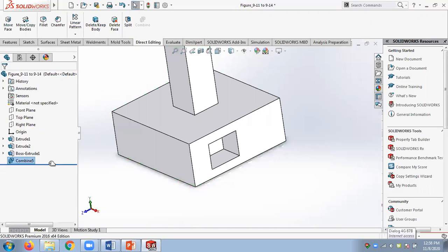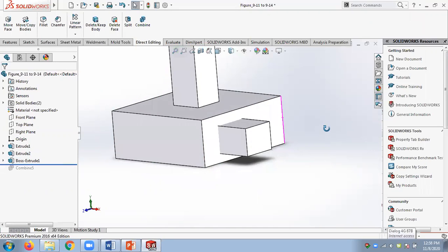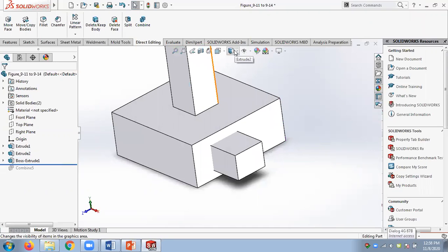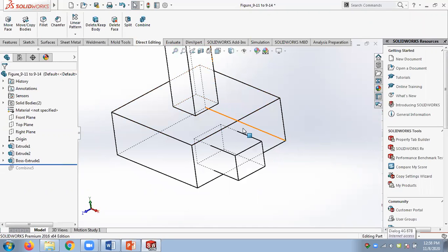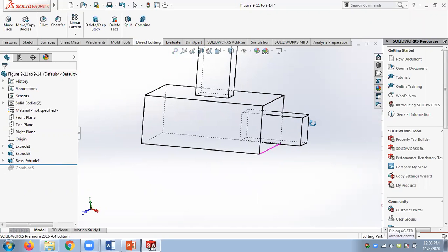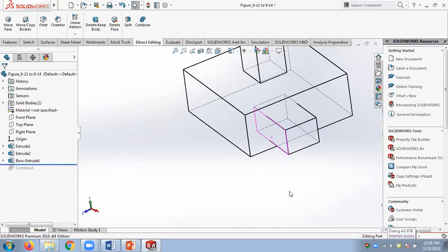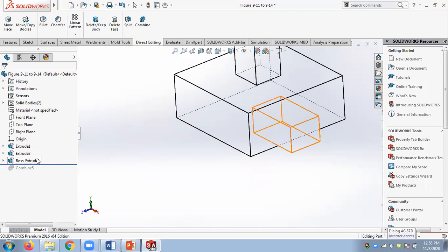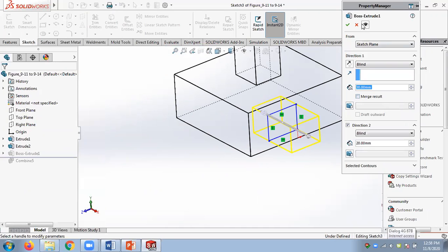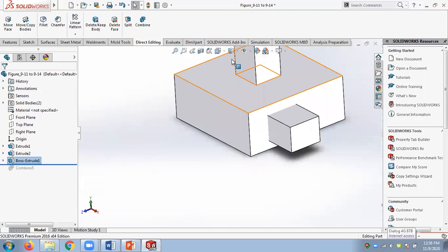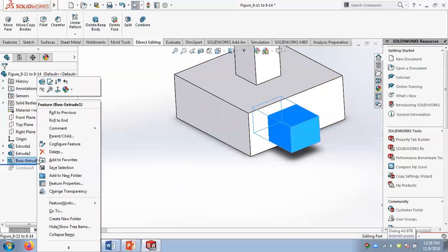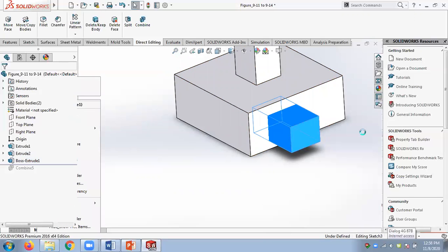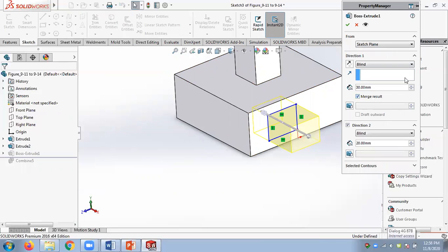So if I just roll this up, you can see this is the part I have drawn going inside a little bit, and I remove the material from the Boolean operations. So you can see I should apply this unmerged tool. Otherwise, you can see these boundaries are not shown because this is going inside. If you merge it, what will happen? I have told this in last week's course.